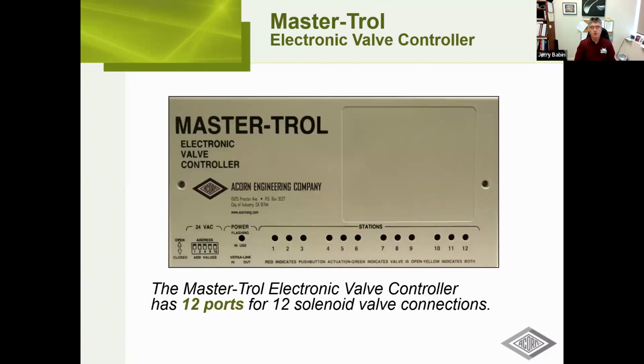So again, when we talk about the Master-Trol controller, it has 12 ports for 12 solenoid valves. When you think of the solenoid valve, a combi potentially has 3 solenoid valves, one on your flush valve, one on your hot water, one on your cold water. So theoretically, this controller can handle 4 fixture combis, assuming you've got hot and cold water. Or if it was running a shower with tempered water coming out, you can have 12 showers connected to this. If you had lavatories, again hot and cold water, you'd have 6 lavatories connected to it. So every solenoid valve would have a connection to the controller.